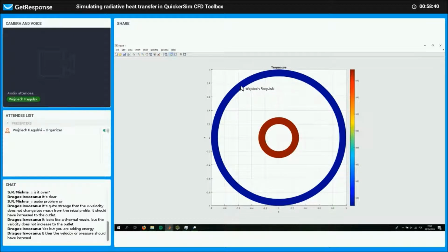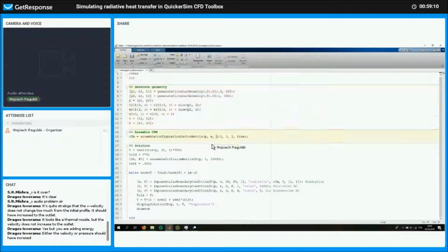And because what you have here is the radiative flux, which, if the temperatures are the same, is very small, obviously, but for numerical reasons, this is not the physical world. This is a mesh. This is discretized. What happens is that there's a small flux, and even such a small flux, because of the stability reasons I mentioned a second ago, the simulation blows up instantly. So in this case, you need to stabilize your solution by adding a way for the heat to escape.